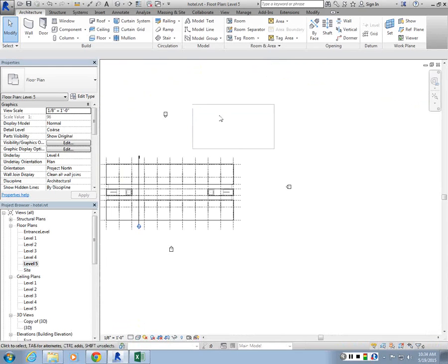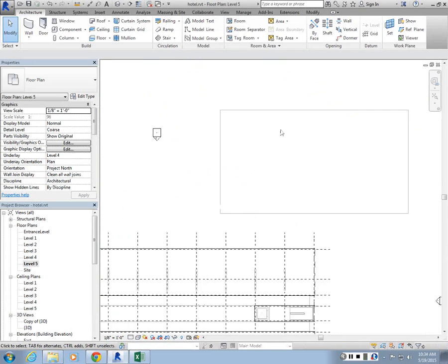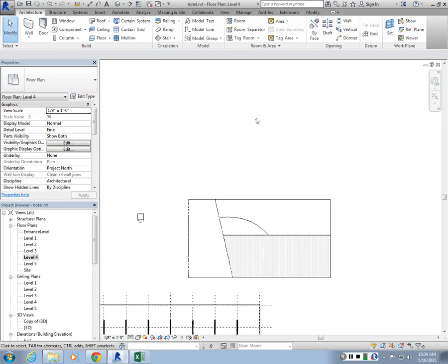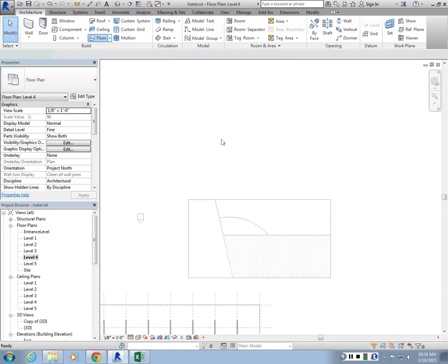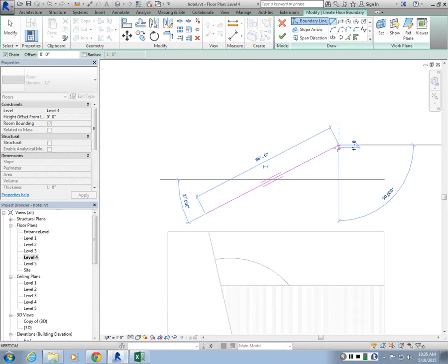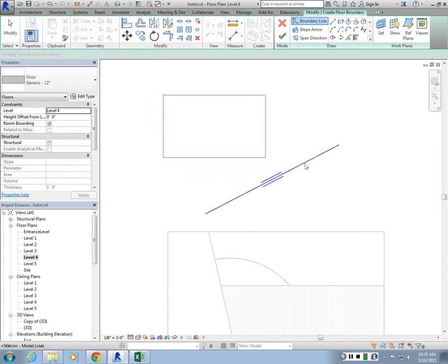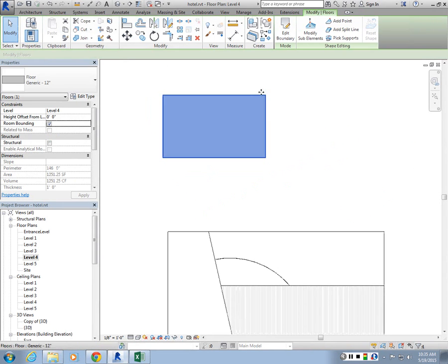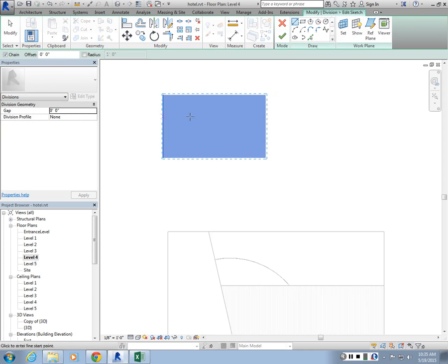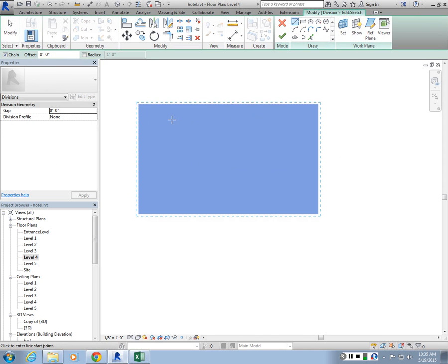Okay, so let's create some floor slabs. Play with the division. The way I did it was: go to architecture, create a wall, create a floor, and then once you're in the floor, create a rectangle floor. After you create the floor, go to create parts, divide parts, edit sketch, draw some lines to divide it up, and then choose the selections.